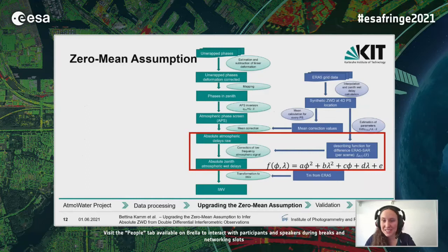I hesitated to just subtract all ramps or anything, because atmospheric signals often look very much like those ramps. And as I'm interested in the whole atmospheric signal, I can't just subtract all remaining signals. So I'm using the ERA5 data to calculate the low frequency part of the atmospheric signal. In my case, for this area, I use a polynomial of second degree, but if you have a smaller area, you could use just a linear function to correct, or for a bigger area, you could think of another function. Here, I used the polynomial of second degree.